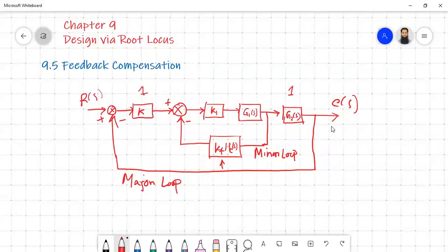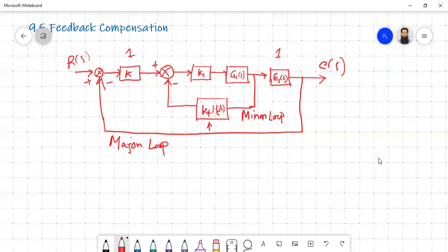So why is feedback necessary? In some cases, our control system has a huge noise signal, which can be amplified if you put it in the cascade zone. So in those cases, we have to go for the feedback compensation. Cascade compensation is not possible if the system has a huge amount of measuring noise, which can be escalated if you put it in the forward path.